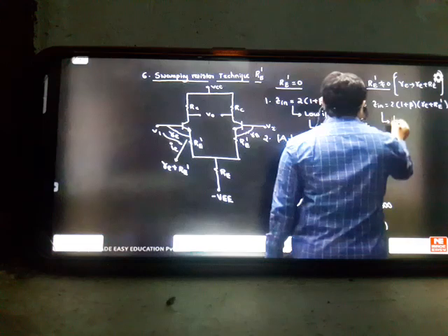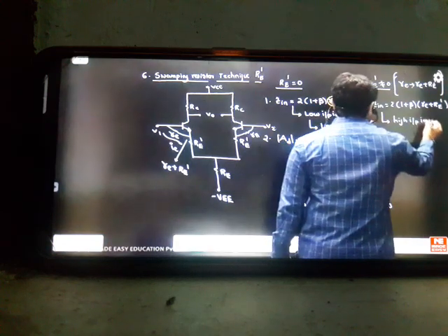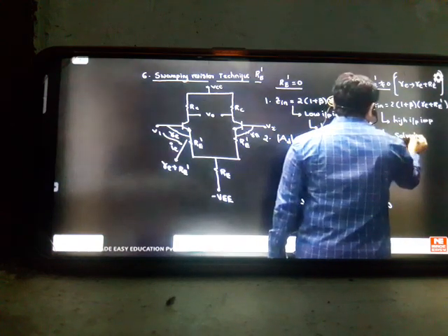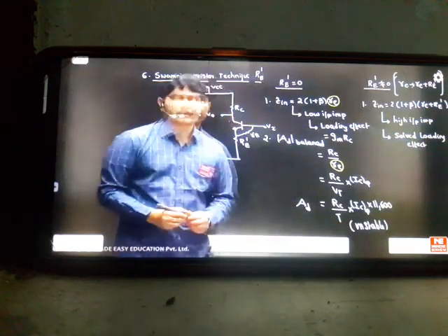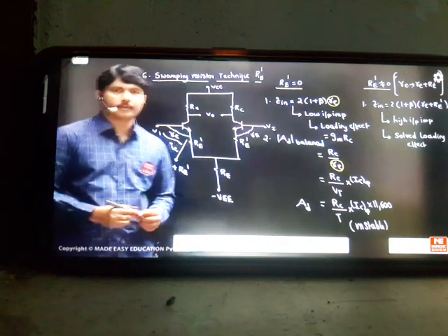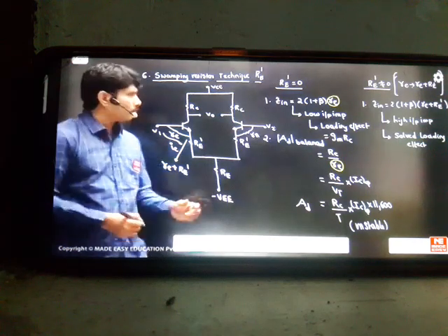So can you see that it became high input impedance? You get mega ohms of impedance, and it's solved the loading effect. So the swamping resistor technique's main importance is to create high input impedance for your op amps. Without the swamping resistor, there would be no op amp design in electronics. So the swamping's main purpose is to boost up your input impedance.